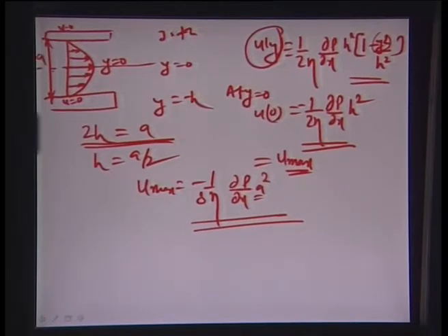So let us now try to calculate the volume flow rate, because this would be important from the perspective of later trying to integrate it onto the electroosmotic flow equation. Okay. And we can also compare the pressure driven flow with the electroosmotic flow, which was really the objective. And in terms of profile, as you will find out in just a little bit, the electrokinetic flow, or the electroosmotic flow, is really a plug-like flow as opposed to the parabolic flow introduced by the pressure driven flow.